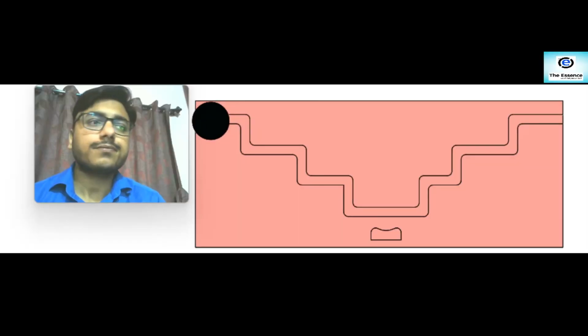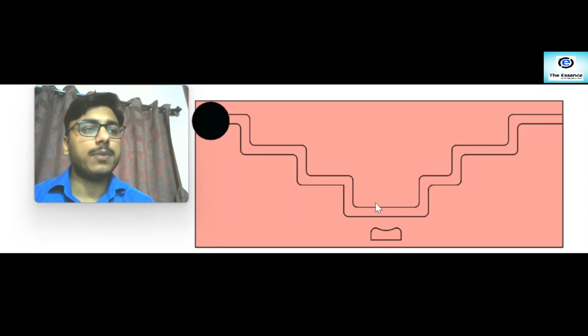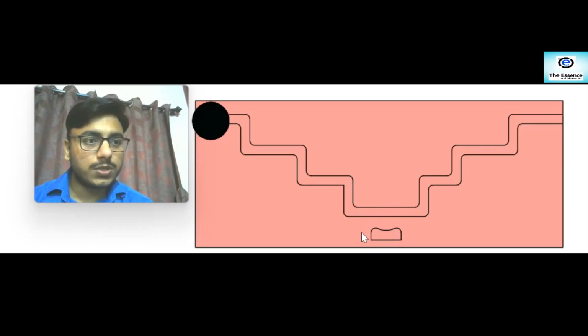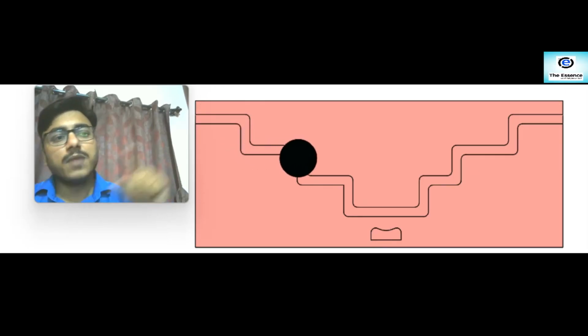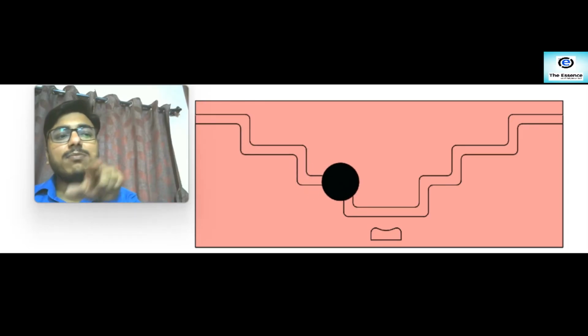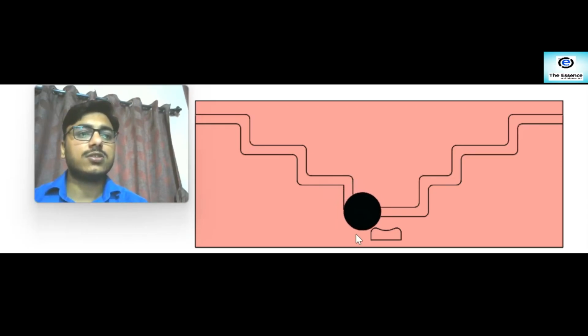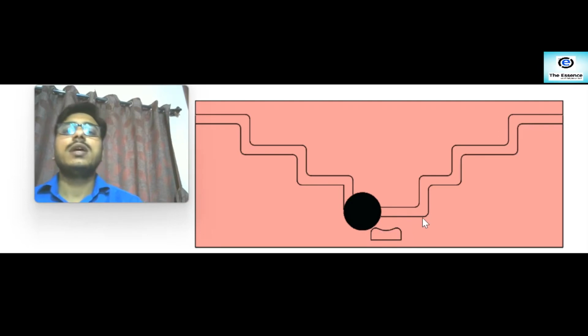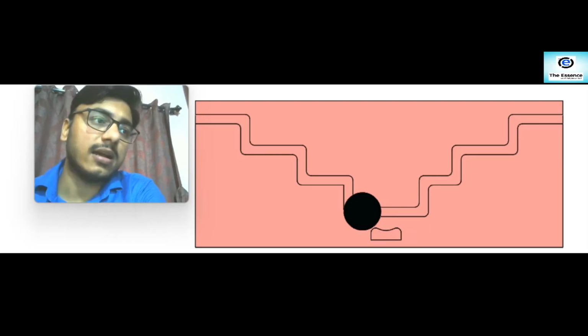Now suppose the worst case got manufactured. In the worst case, what might happen is that this slot moves too close to the protrusion that we discussed. So it may be possible that these are too close, and when the cam moves in the assembly and goes through that protrusion, it may be too near to each other and get stuck over there. It does not pass through because of the dimensioning methodology, as this slot and this feature are too near to each other. So that might be a scenario, and we need to counter this with tolerance stack-up analysis.